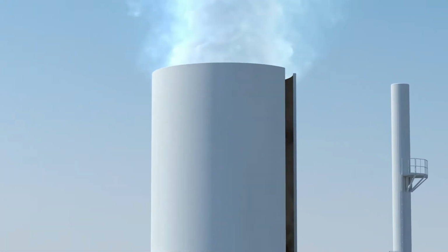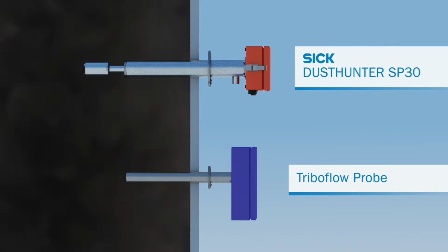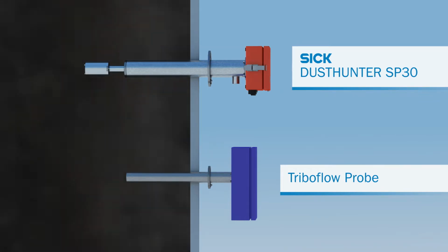For the measurement of dust, which occurs with emission gases, there are a large variety of measuring devices and providers. Measuring systems detect dust directly in the flow of gas by means of a measuring probe. The reliability of the measuring results is as varied as the measuring principles themselves. A large number of the devices available works according to the triboelectrical principle. SICK goes a different way.